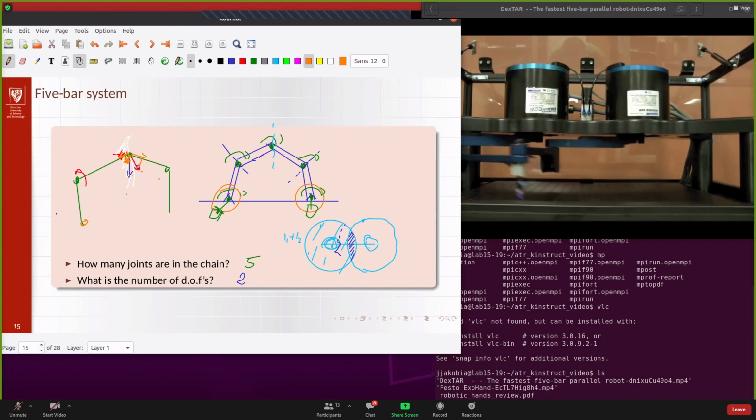So the bigger part of the force applied to the end effector is compensated by the mechanical structure itself. And because of it, the non-compensated part, the perpendicular part that needs to be compensated by the thickness of the arm to prevent bending, is much smaller. Therefore, again, the arms can be lighter. And because of that, we get a higher stiffness of the mechanism and higher precision.